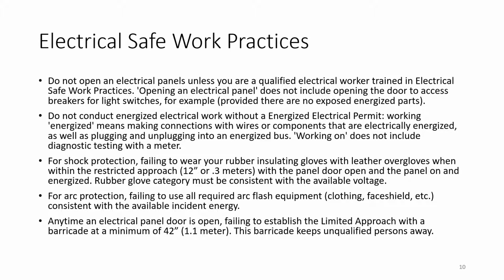Electrical work practices. Do not open electrical panels unless you are a qualified electrical worker trained in electrical safe work practices. Opening an electrical panel does not include opening the door to access breakers or light switches, for example, provided that there are no exposed energized parts. Do not conduct energized electrical work without an energized electrical work permit.